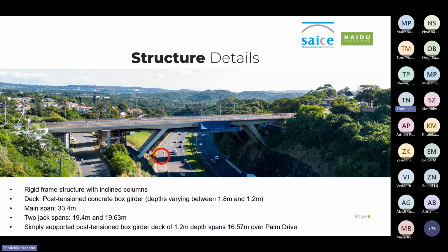This Class B fire reached alarming heights, leading to visible damage such as concrete spalling, cracking, and delamination of the soffit and the piers of the bridge, especially on the main span. And although the damage was concentrated on a specific section, the overall durability implications were quite severe. And that's what prompted our detailed assessment and sustainable repair strategy that I will discuss next.